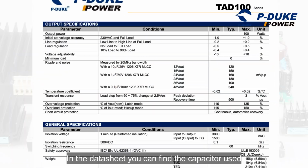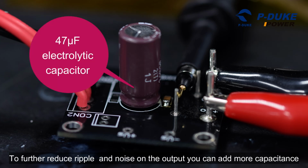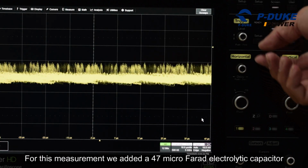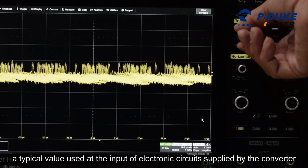In the datasheet you can find the capacitor used for ripple and noise measurements of a specific product. To further reduce ripple and noise on the output, you can add more capacitance. For this measurement we added a 47 microfarad electrolytic capacitor, a typical value used at the input of electronic circuits supplied by the converter.